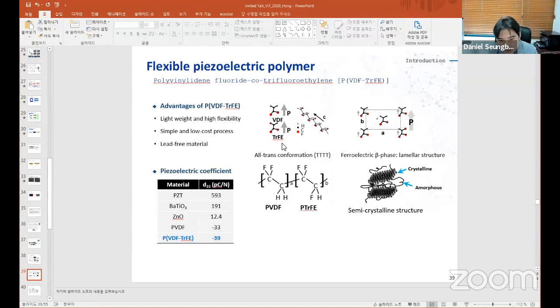And do hot press, then we can do the same with PVDF-TrFE, polymer piezoelectrics with, let's say, nickel-coated or copper-coated or some type of conductor-coated fabric. So if we have fabric, piezoelectric layer, fabric, and we just hot press them, that will be the simplest process we can think of. And I don't think I have to remind you of the physical properties of PVDF, but